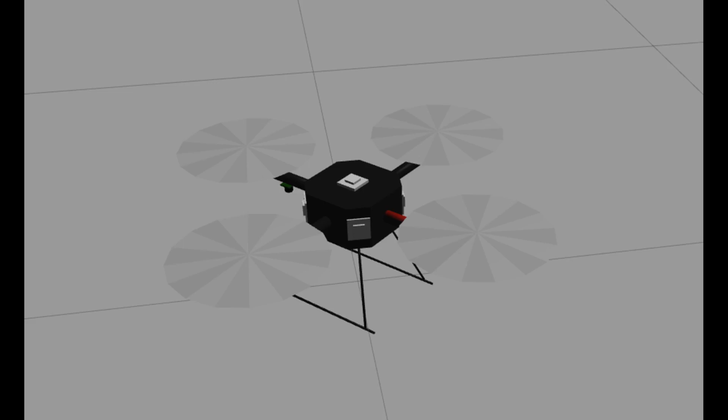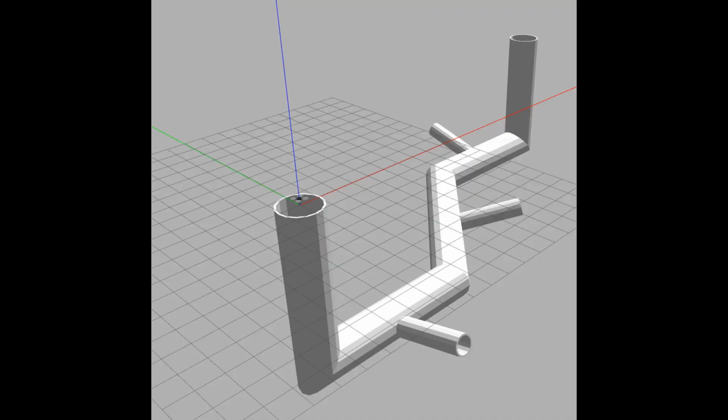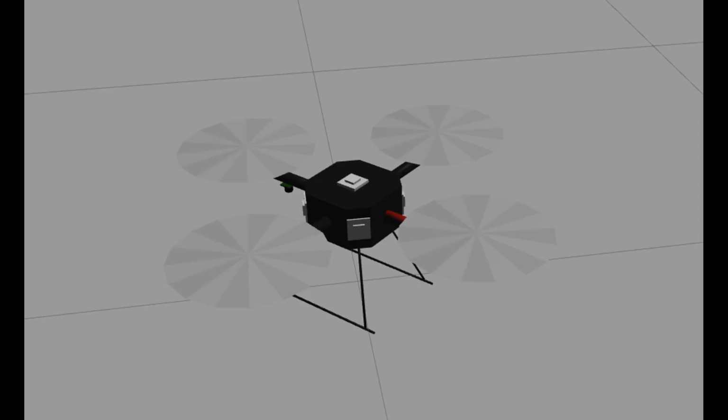Let's try out the potential field method in another scenario. This is a simulated drone in ROS called Hector Quadrotor, developed and maintained by TU Darmstadt. I created a tunnel environment with Blender. Instead of a laser scanner, I equipped the drone with 4 multi-zone ranging sensors, the grey boxes on the drone, with a field of view of 65 degrees.